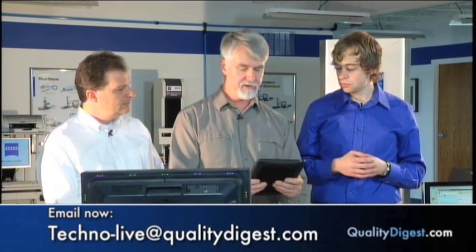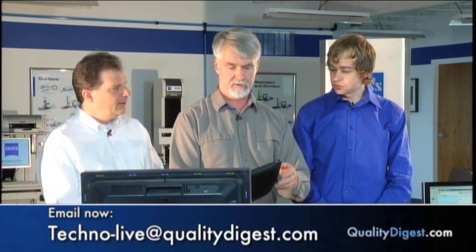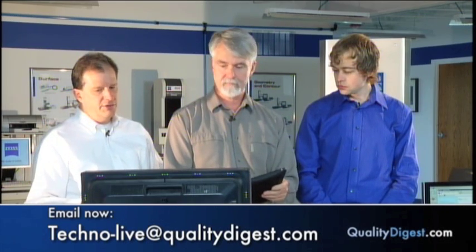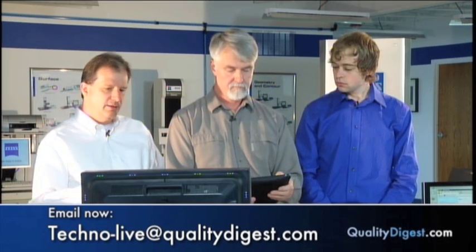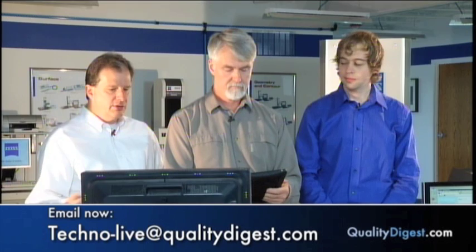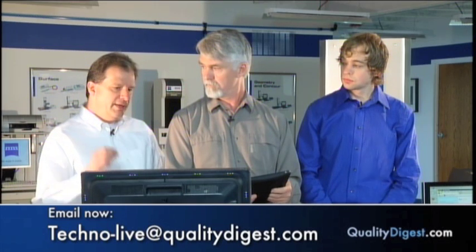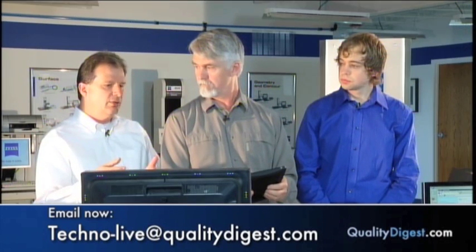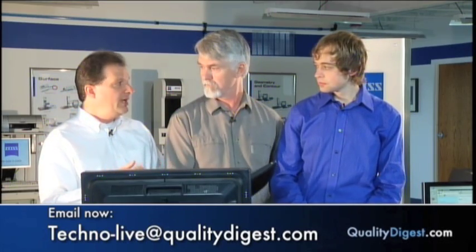Yeah, I think this obviously must be for the Surfcom. What is the measurement uncertainty and resolution, from Chris? Well, it's hard to put a number around an uncertainty. We would have to look at the actual type of part that they're measuring and the amount of the gauge range that we're using. But the standard resolution using all 5 millimeters of range is 16 nanometers. That can be improved by simply reducing the range we use. So if we have a really tight roughness we need to measure, we can shorten that range and get up to about 3 angstroms of resolution.